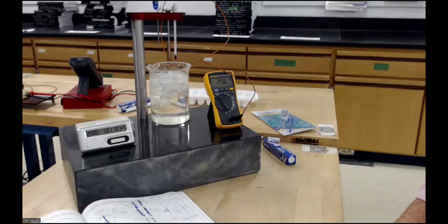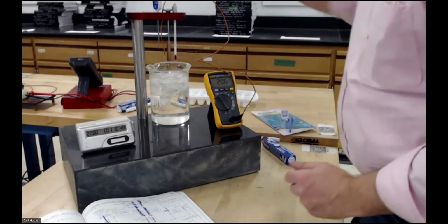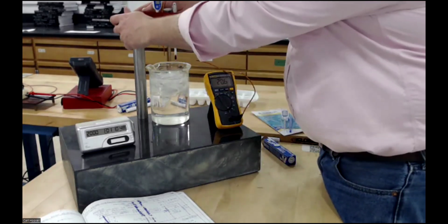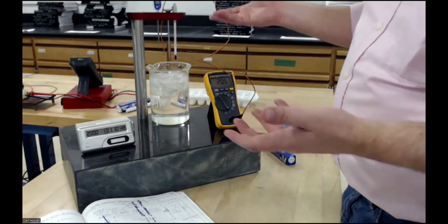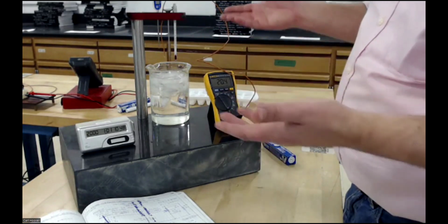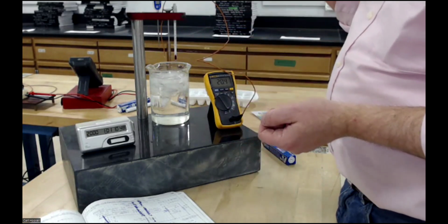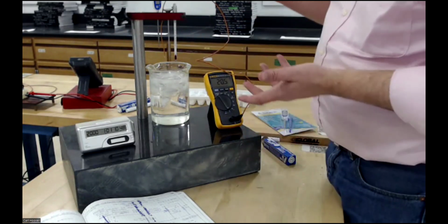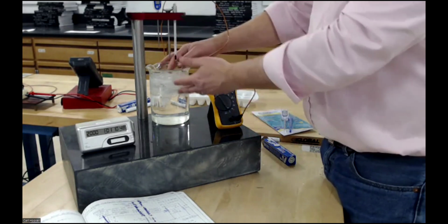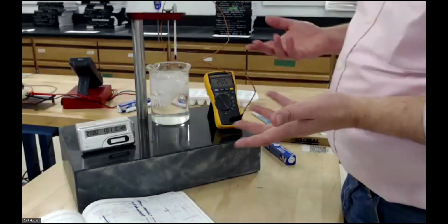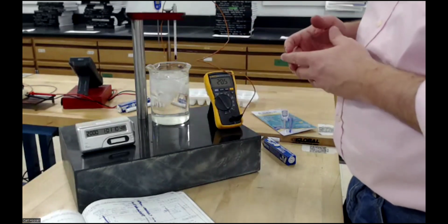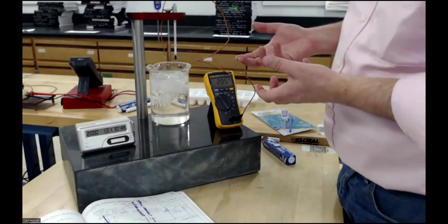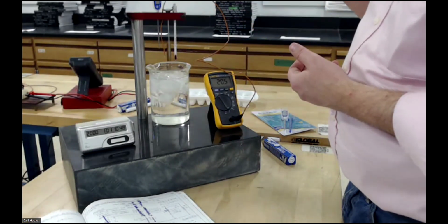So the experiment is really simple. With a camera on, you're going to simply record a video of these guys as you plunge them into water. One important thing is to make sure they're all at a steady state room temperature for a certain period of time where the temperature is not changing. And then you want to plunge them in and record the time it takes for them to come to a stable temperature of the ice bath. Now, I just put the ice in, so it should be pretty close to ice temperature, but at the end of the day, the actual temperature doesn't matter. It's that we can measure the response curve as it goes down.